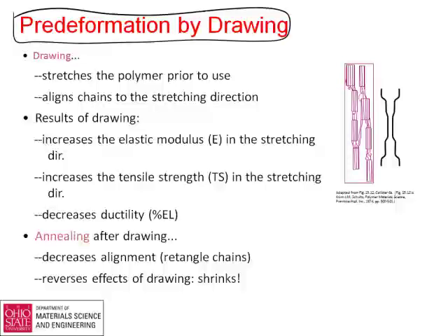And basically what we do is we just take the fibers and align the polymer chains very well along that direction. It gives us very, very high strength, very, very high stiffness. And if you make a mat of this material and a bullet tries to get through it, it basically can't because those fibers are so strong. Turns out that hardened bullets, like steel bullets, can get through it fairly easily. So for military grade stuff, we use ceramic in front of this. But if you have a lead bullet, it'll spread out the lead bullet and cause it to stop.